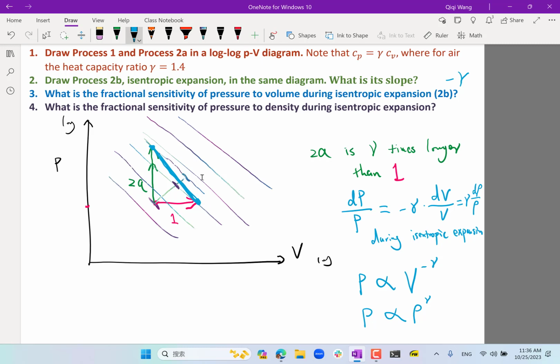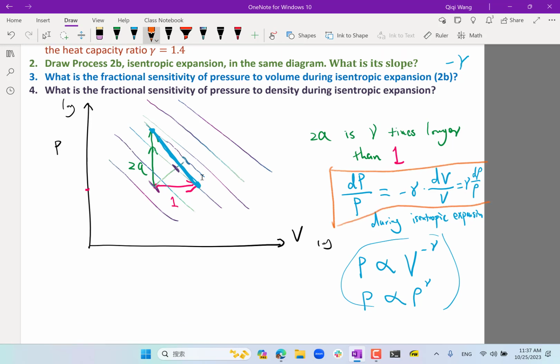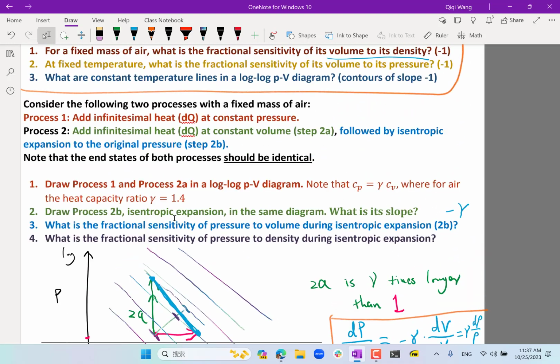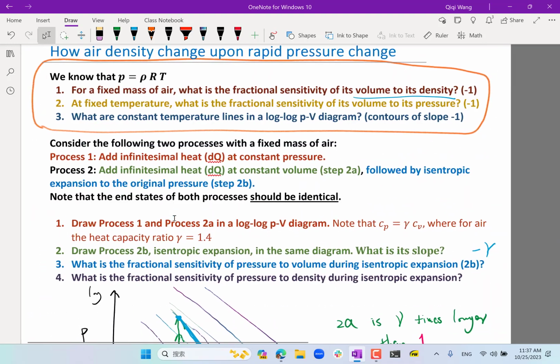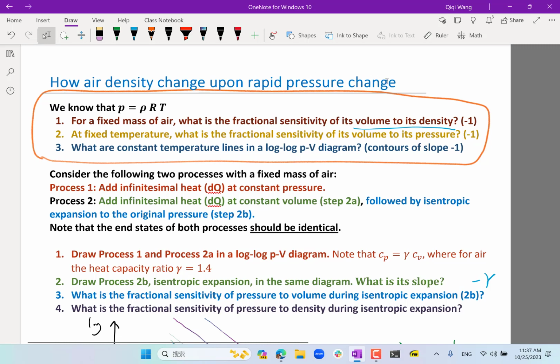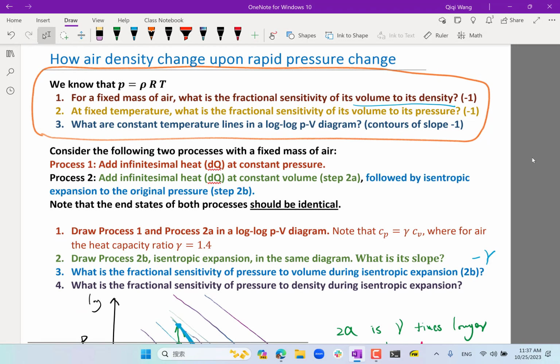Okay. So we're not going to be using the integral form a lot, but we are going to be using the differential form quite substantially in compressible flow. Why do we care about isentropic expansion? That is because the pressure change is very fast in terms of time during typical aerodynamics. The conductivity of air is actually quite poor. So for heat to go from a high temperature region of the air to a low temperature region of the air through conduction takes a relatively long time.